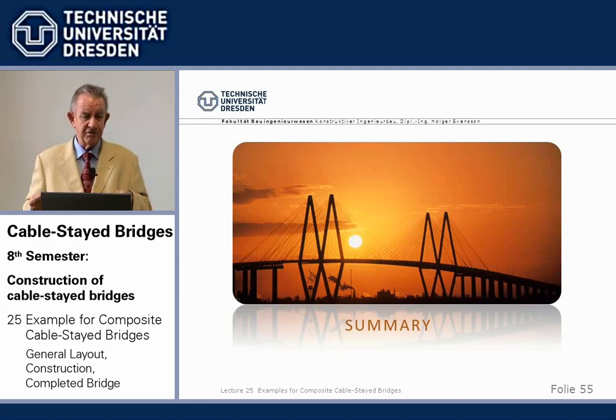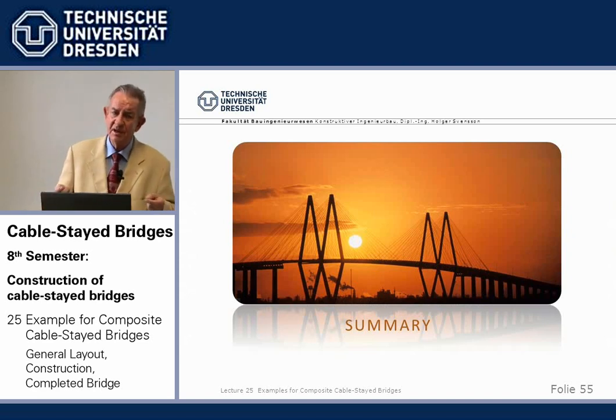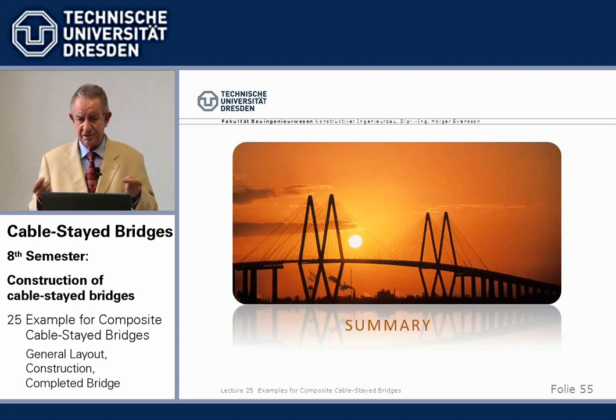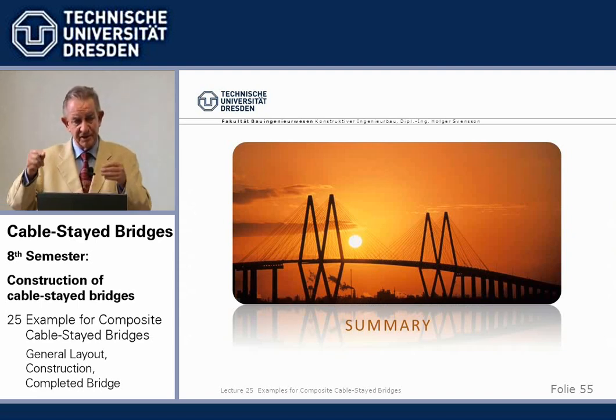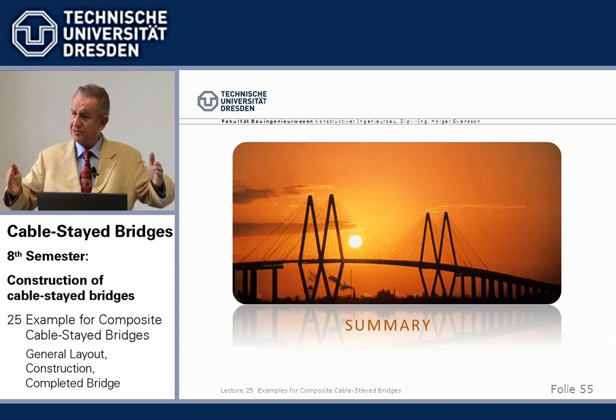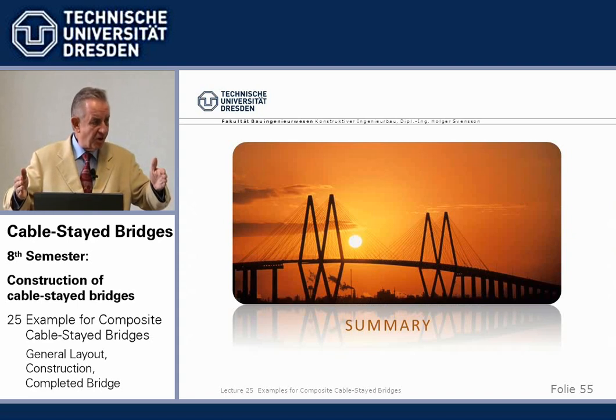The alternate, which I found is more economic, is to use a deck from precast slabs resting on the cross girders, with cast-in-place joints, which are certain disadvantages, but because of the natural compression from the stay cables, they are under compression virtually all the time.